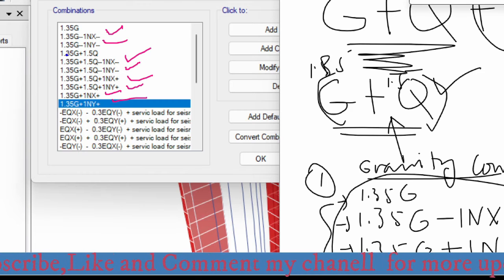And the other is this one. That is, we need to put one extra load combination excluding the notional load, because we will use this load combination while we will be excluding the notional load in all 4 directions. So that is why 1.35 permanent load plus 1.5 variable load combination is placed here, just like this.